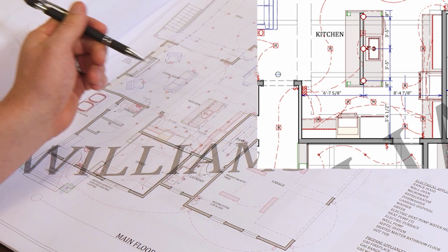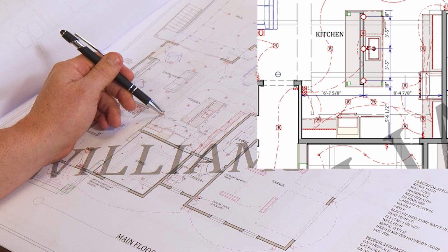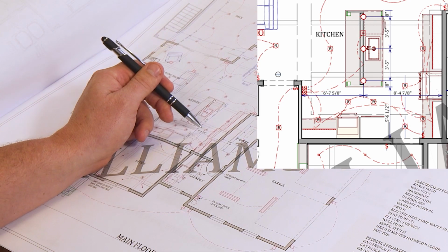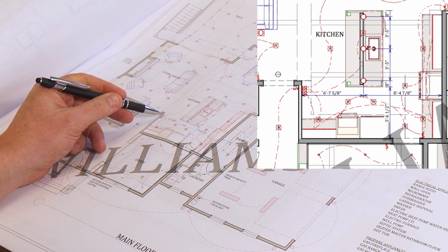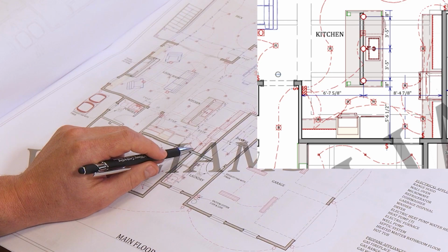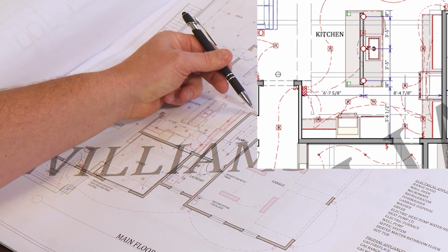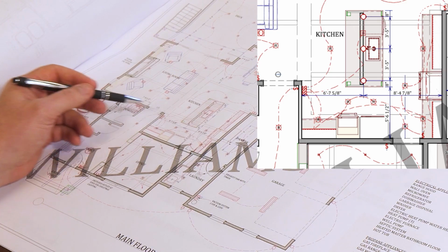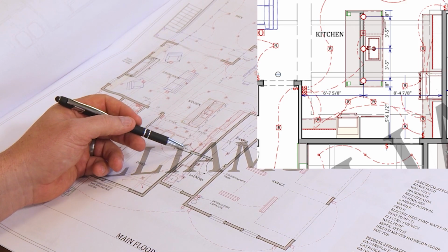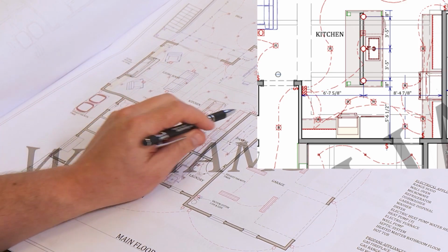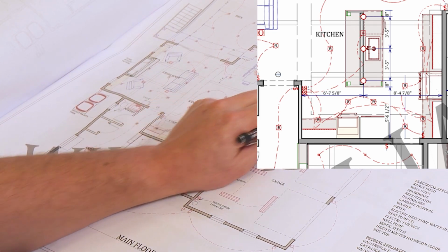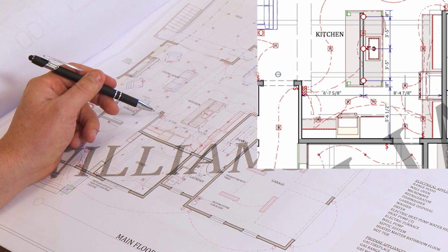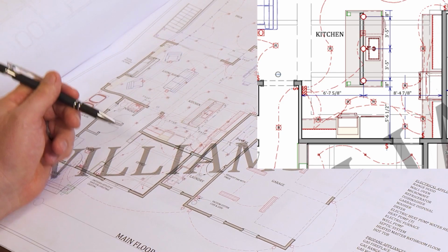Let me show you an example of this 4-way switch. This 4-way switch comes down and is connected to all of these can lights within the kitchen area. But we have a switch that's here, then it switches in this location, and it switches at this location. So if you're in the living room, you can turn it on. If you come in through the front door and come in through the office, you can turn on these main lights. Or if you're leaving or coming in from the bedroom side and the garage side, you could do the same. Now, in this instance, that's the only 4-way switch leg.